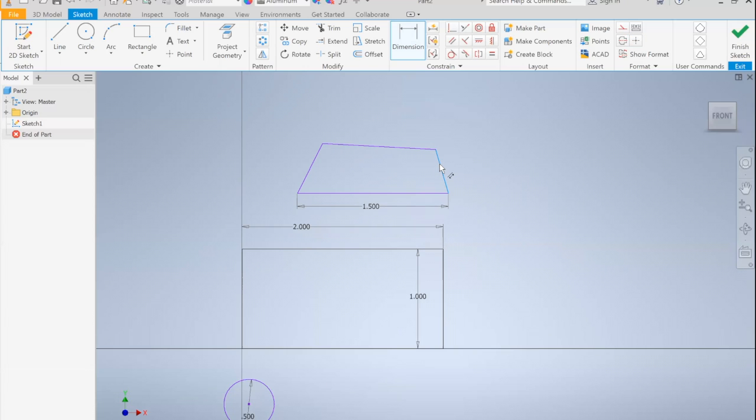Let's say I want this to be half that. I can say base divided by 2. And now it's going to be exactly half that. And here I can click this; you have to double click slanted lines in order to get the length of the line and not the perpendicular distance. I can set this to base divided by 2 as well.